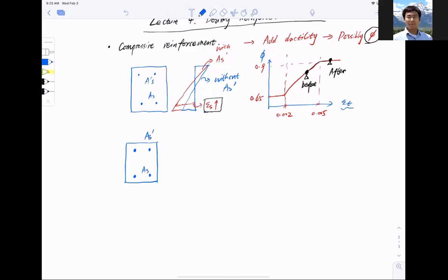Okay, inside the doubly reinforced section, the strain is going to look similar to the singly reinforced section. This is epsilon Cu, and mind you that is 0.003, and I have a steel strain here, epsilon S, and I have the actual compressive zone C. Now I have a little bit of additional things, and that is epsilon S prime. Of course, for the internal stress distribution, I have a Whitney stress block again. This is 0.85 F prime C, nothing different. And I have an actual compressive zone A, and I have a stress in the compressive reinforcement steel, F prime S.